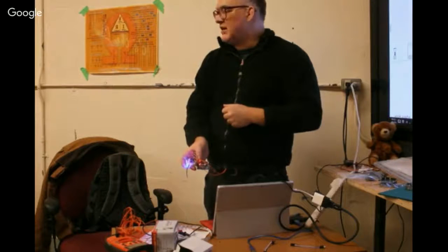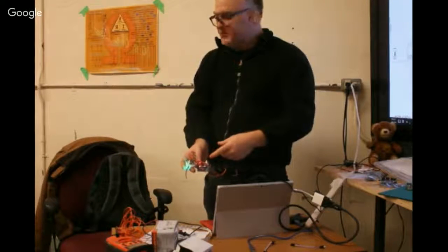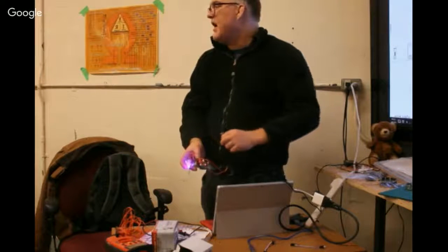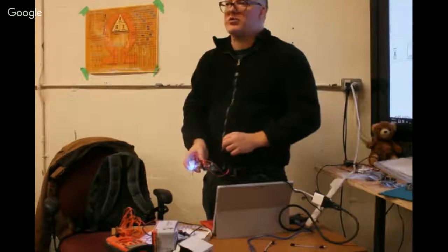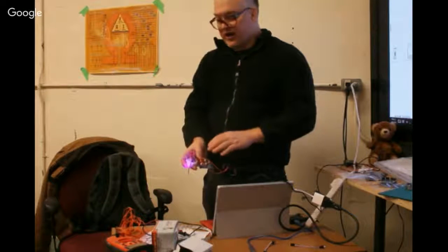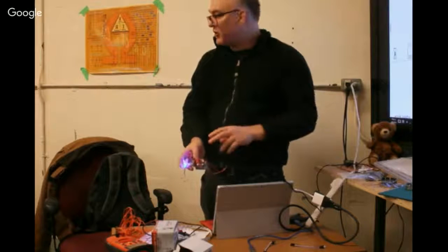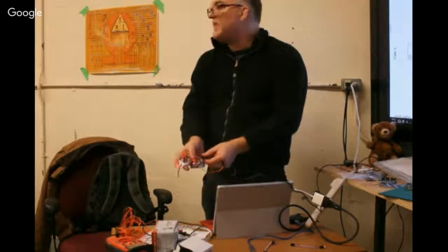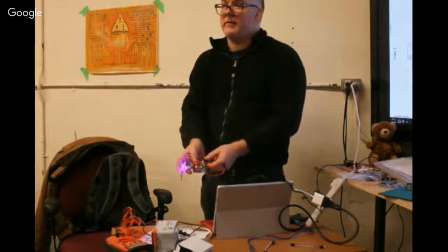And so if you plug your LED strips in, they won't even light under 5 volts because it's a string of 3 LEDs. So don't expect that to work when you're actually plugged into the USB port. So the way that we'll do it for this project tonight is we'll plug into the USB port, we'll download the code, we'll unplug from the USB port and plug the external power supply in, and then do the rest of the circuit from there.